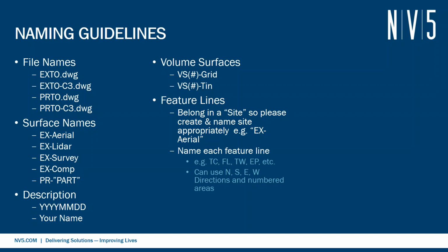Never change the creation date for modification. Add the modification data to the data that's already there, or a brief description of why it was modified, right? Say, hey, new contour data or additional survey data. But we need to be able to trace our workflows and the modifications and revisions and why they happen. So let's be a little bit more descriptive in some of our descriptions. It's built into the software. The developers were insightful enough to see that, so let's utilize it.